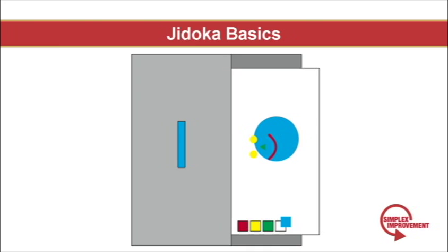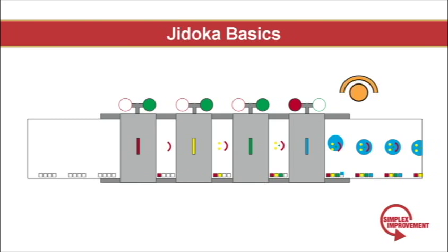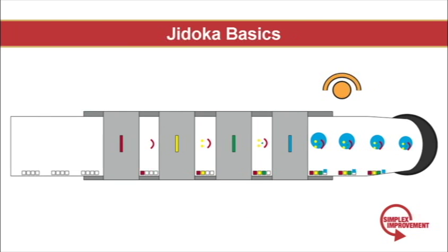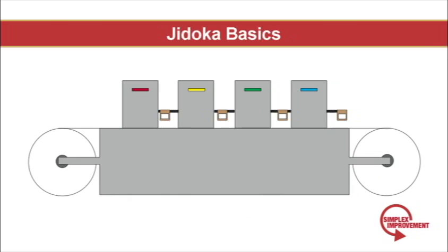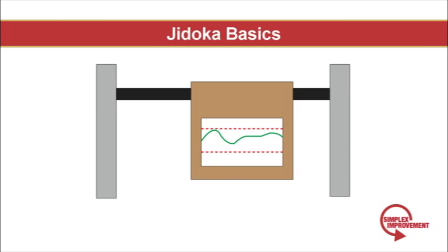If one or more of the colored squares don't line up, it means the printed image is defective and must be discarded. So at the recognition level of Jidoka, the machine would detect the color box being out of the expected area and sound an alarm for the operator to stop the machine. In the action level of Jidoka, it would warn the operator and then send those defective images to a separate waste bucket. In prevention Jidoka, the image would be continuously read by a camera system. A sensor would send the signal back to whichever print tower is drifting out of spec and adjust it before defects were generated.